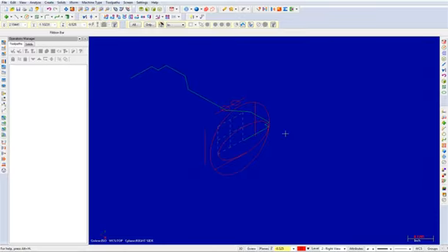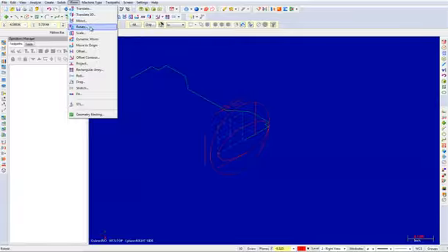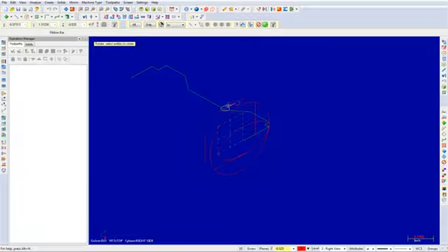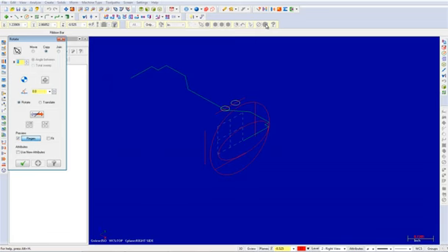Now select the Xform Rotate command and pick the 2 arcs we just created. Hit the End Selection button once complete. The Xform Rotate dialog box will appear. Match the parameters as shown and press Enter. Ensure copy is enabled, the number of instances is set to 3, and an angle is set to 90 degrees. Now select the OK button to exit the command.